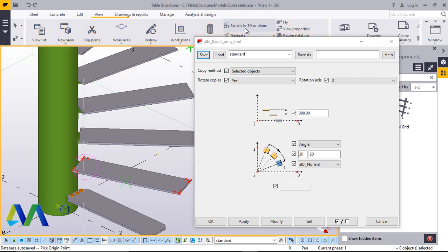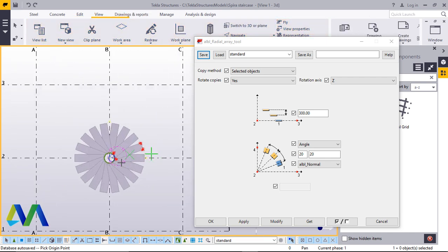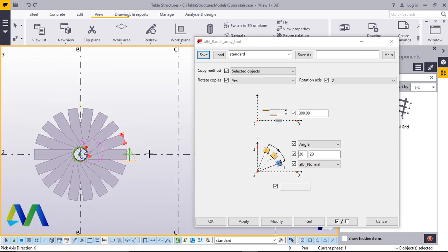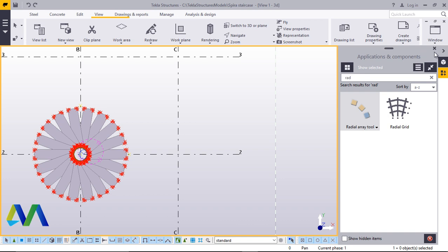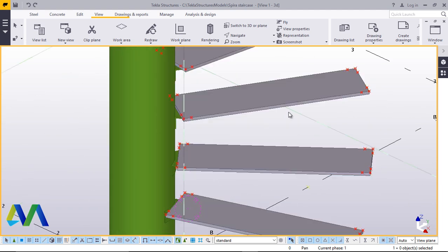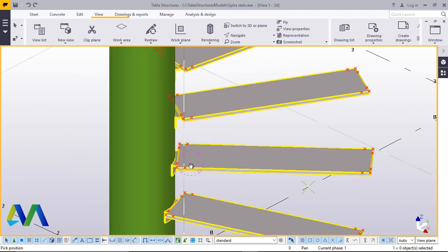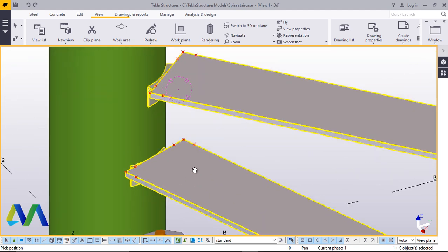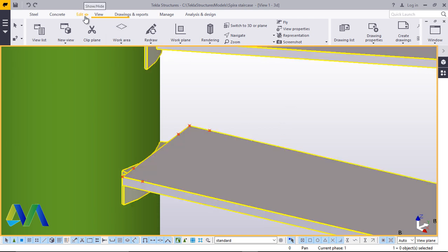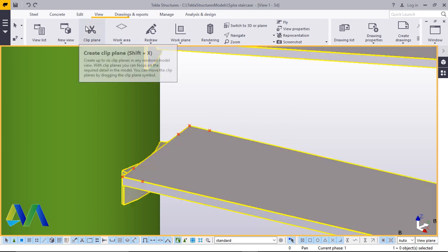come to view, switch to your plan view. I'll snap right here, then select my x-axis, then come to y-axis. Perfect. I've created, you can see the spots we created. Now I'll do away with this by applying and accepting it, then close that dialog box. Then I'll switch back to my isometric view. These points will assist us in creating or in chamfering and creating the bolts. Now from here I want to go straight to chamfer all this, though it will take time, but the best thing is for you to get the concept of doing this.